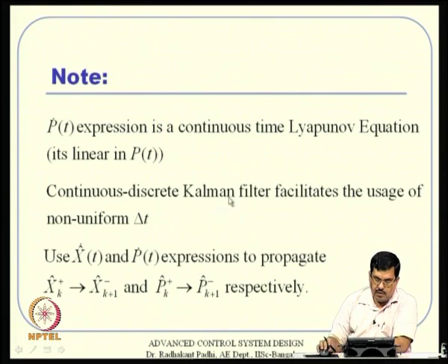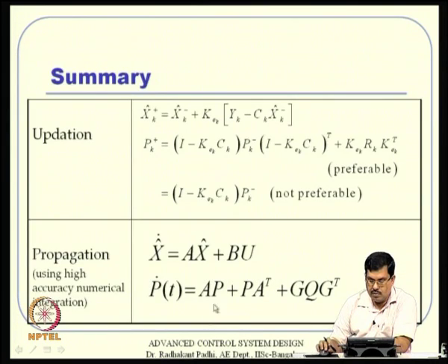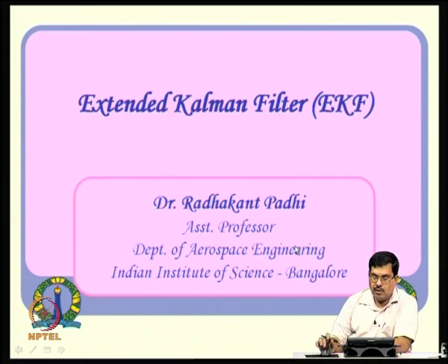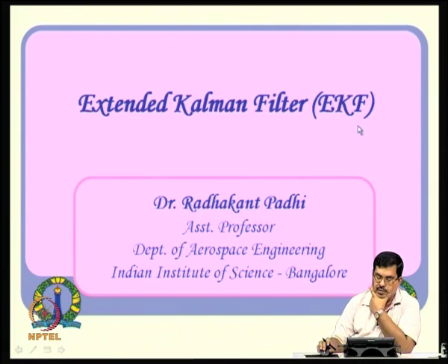Also, this is what I already told, and what it tells is that the P dot expression is a continuous time Lyapunov equation. If you see this, it is no more a Riccati equation basically. It is in a continuous-discrete framework, and it turns out to be nothing but a Lyapunov equation. Now, finally, with this information, we will be able to touch upon the extended Kalman filter, which is very popular in industry, and most of the time people use that extended Kalman filter.